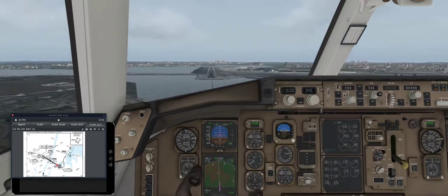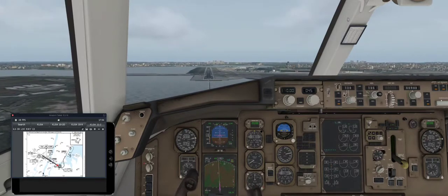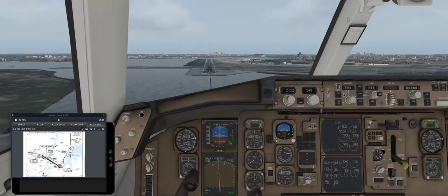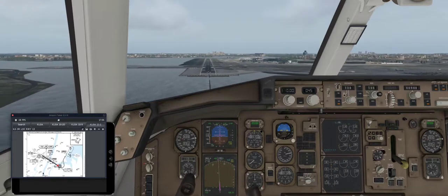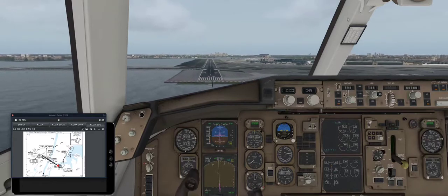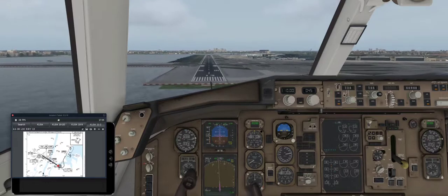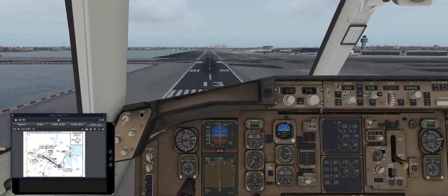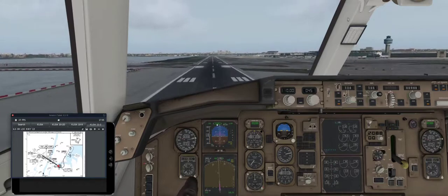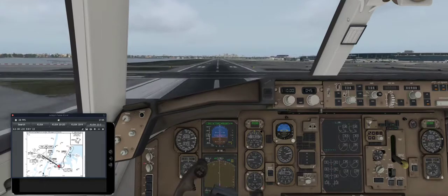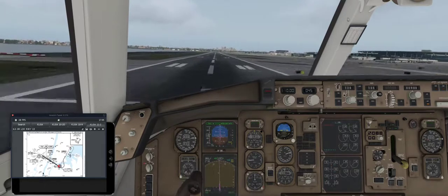Here we go. Looking good. There's no reason to take minimums. Minimums means you've reached the point now where you're landing whether you want to or not, although I've aborted from a landing beneath minimums. Here we go, and watch now. 50, now it's on 40, flare. 30, 20, 10. Watch vertical speed as we get close to the ground, and I said we'd do that.